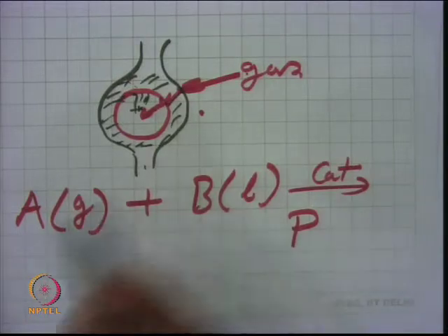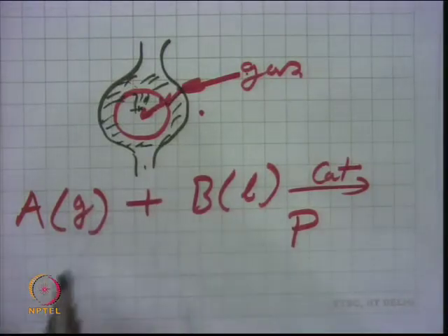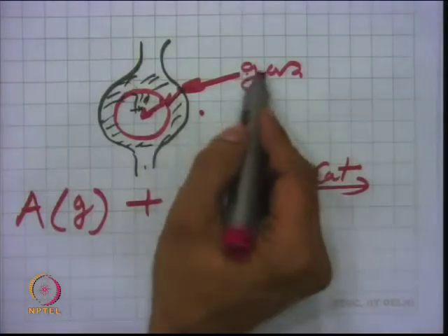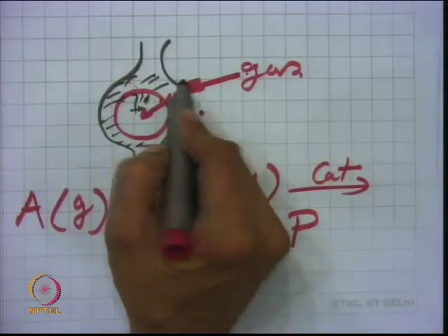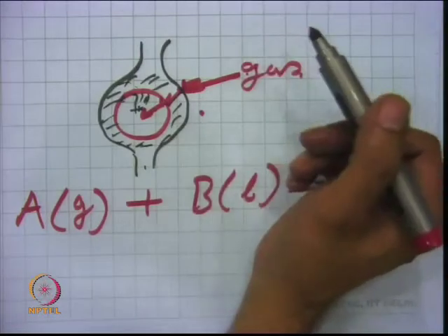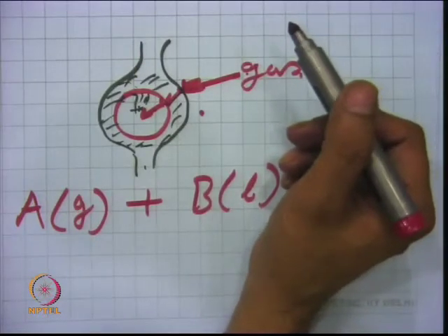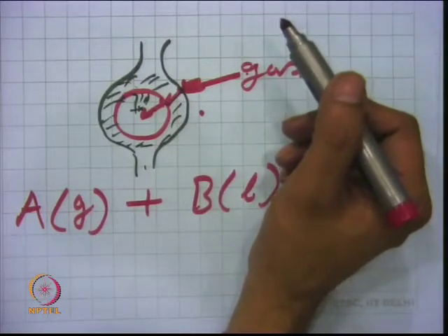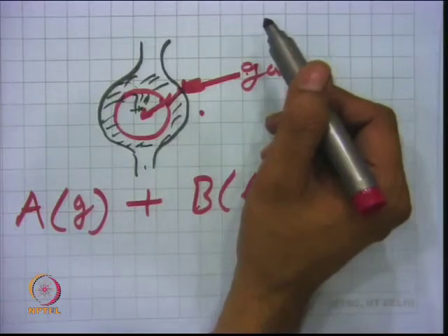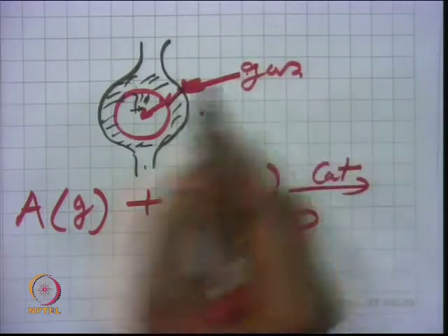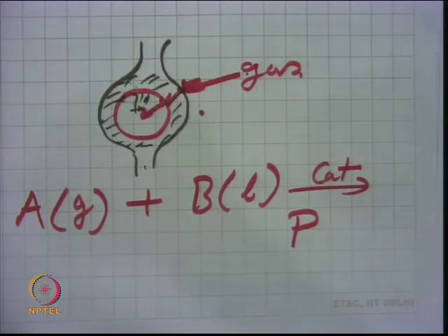So, this is what we have to look at: what are the resistances offered, because it is mass transfer dominating, because the solubility of the gas is important here. This is something like kerosene hydrogenation, or removal of sulfur from the kerosene, diesel hydrodesulfurization. So, we need to look at the solubility of hydrogen in diesel, and then the